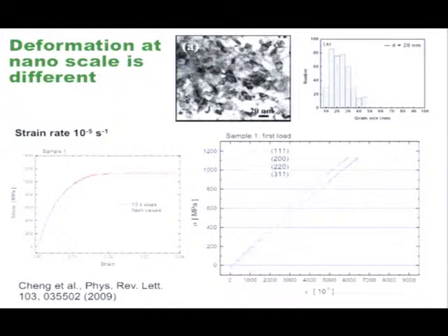Well, I think you have to be careful. These Lorentzian parts are not necessarily associated with grain size. As Thomas pointed out, if you have a short-range stress field, you will have a broad distribution, more or less like a Lorentzian. So in order to derive numbers, parameters from your peak width analysis, you really need to go through the details, not just use it as a black box, and look at your system and see whether or not the parameters you extract really make sense.